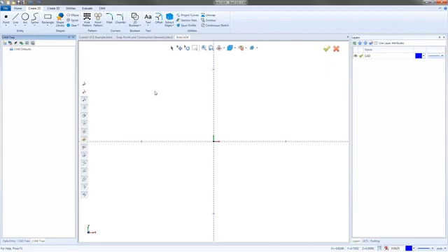But you'll still have the same problem that everyone's had in the past, which is if you want to bring it back, you have to know how to bring it back. And the trick to bringing it back is the same as it's always been. Go to an empty part of the toolbar up top here, and then right-click, and then just turn the Art Manager back on, and it's going to pop back up in there. So you could turn it off. You could leave it off, especially for those of you who don't own BobArt, there's no reason to leave it on the screen all the time. So you could turn it off, and it'll stay off.